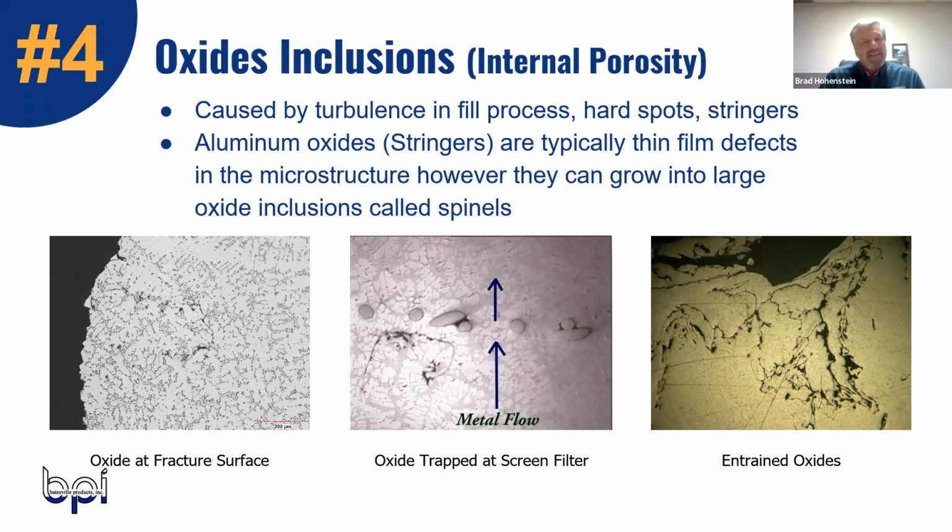Not necessarily. We had a vacuum cast. Anything that you need to fill the metal fairly fast, we were filling blades that were 10 thousandths thick, and if you picture that, that's going to freeze off very quickly. So we have to fill it very fast, but without turbulence, and we were riding right on that edge. A die cast is squirting the metal in there very quickly. You can get oxides in the die cast. The permanent mold, if you have a good smooth fill, you're fine. If you're pouring in a sand casting and you're pouring too high, or your gating's not correct and you're filling too fast, you can get the oxide. So it can happen in anything, but the faster that you fill, the more prone you're going to be to having them.